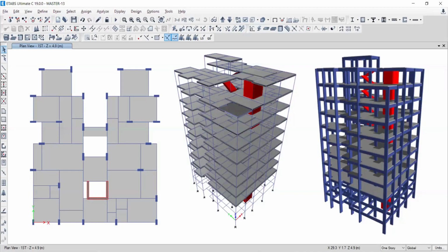The very first is actual modeling of the staircase. The second one is, instead of actual modeling of the staircase, they model a normal slab. And in the third situation, they do not model the staircase or the slab; they do the calculation separately, and that calculated value is assigned to the supporting member. These three options of considering the staircase in your structure, we are going to cover in our training program. After this training program, you will know everything as a real project consultant does, right?